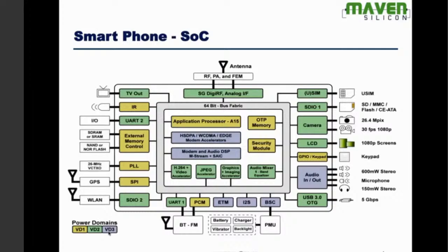There is another way. Look here. There is a dedicated power management unit. Basically, it runs the chip in different power modes. For example, if you are not watching video, then the video accelerator might not be active. The moment you watch video, the power management unit will try to bring up the video accelerator. So it may want to restore the past information. That's what the power management unit does.